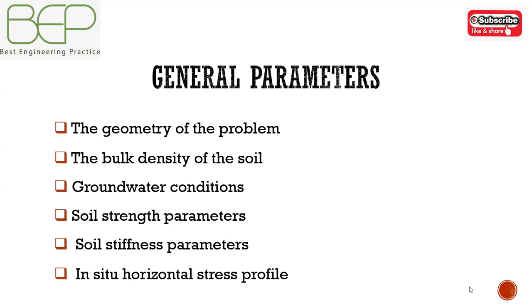In-situ horizontal stress profile. When computer analysis involves constitutive soil models based upon both elasticity and plasticity, it will be necessary to have detailed knowledge of soil stiffness, effective strength parameters, and the initial in-situ horizontal stress. In-situ horizontal stress is both difficult and expensive to measure and can usually only be derived from either self-boring pressuremeter tests in situ or from suction tests on laboratory specimens.